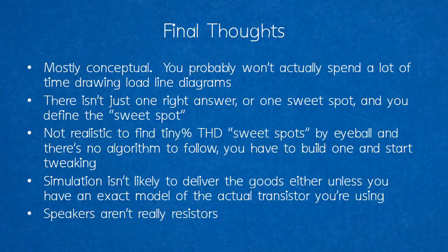It's not realistic to think that you're going to eyeball 0.1% THD on a load line diagram, and there are no algorithms to follow or formulas to plug in. You have to build one of these and start tweaking until you find something you like.